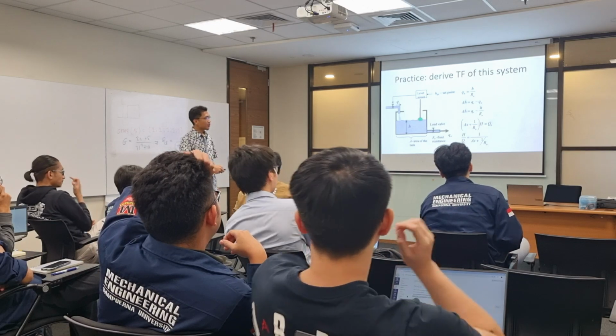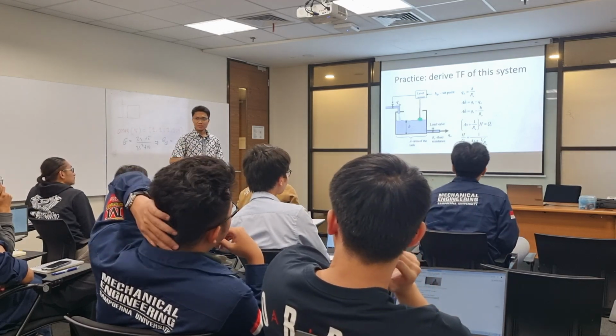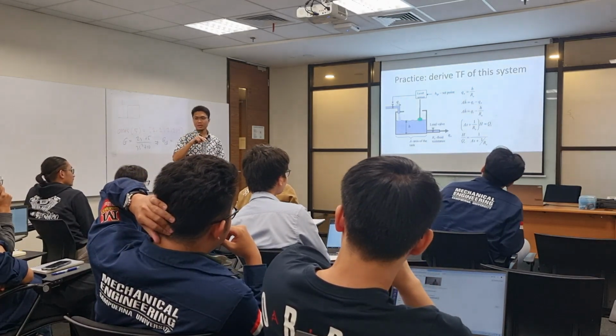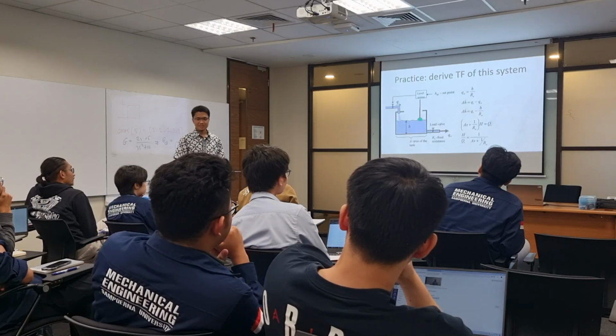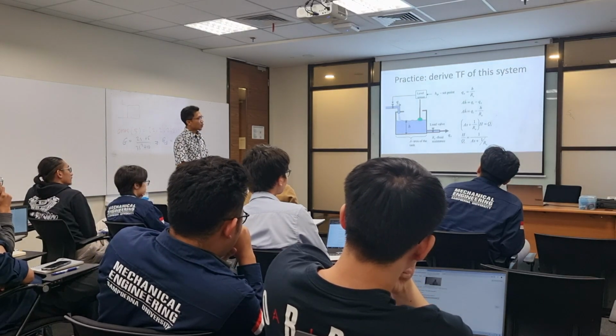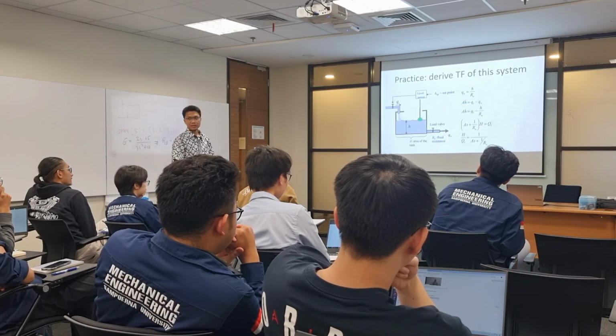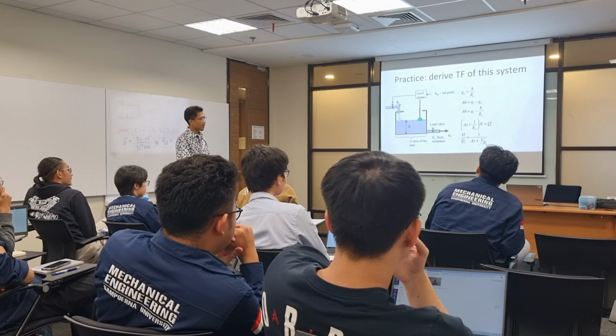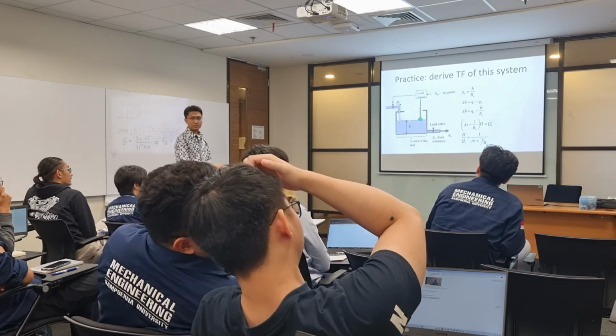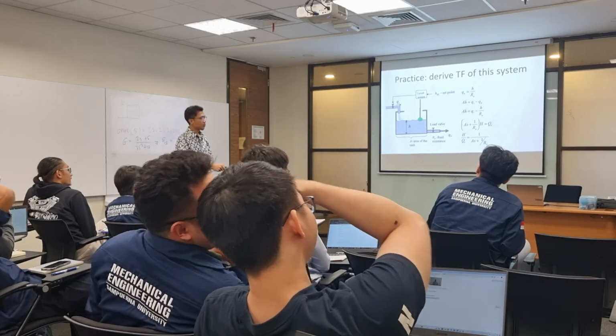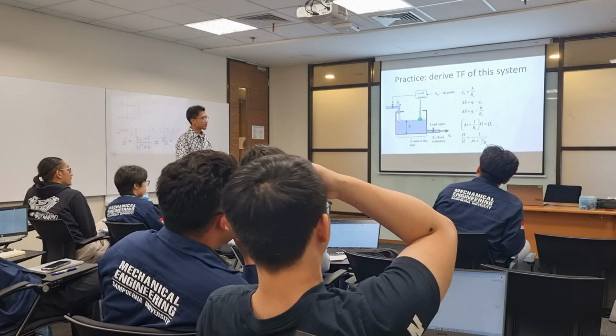Okay, if input is bigger than output, increasing, right? If it is smaller, decreasing. That's correct. So only from here we derive the transfer function. Yeah, you replace the Q0 by H over R0. Yeah, Q0, you replace it by this.